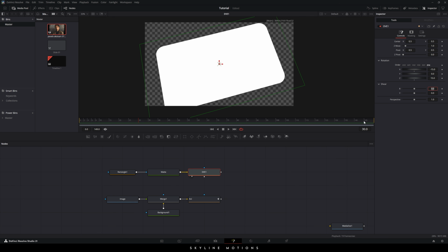So first of all, maybe we will place the CTI on the frame number 45, which is equal to 1.5 seconds, which is good enough for now. Let's turn on the keyframe for all the parameter X, Y, and Z at frame number 45. Then just go to very first frame of this animation. Keep the X value -15 as it is. So just click on the diamond button.